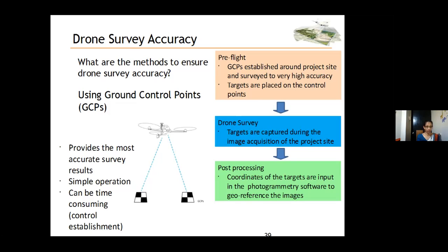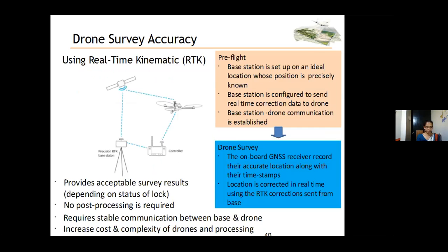That is normal. Relatively new advances in drone technology are specifically their integration with GNSS technology. We can use real-time kinematic and post-processing kinematic methods in order to increase the accuracy of our outputs. This method can make the process easier, safer, and less time consuming when compared with the normal ground control setup process.